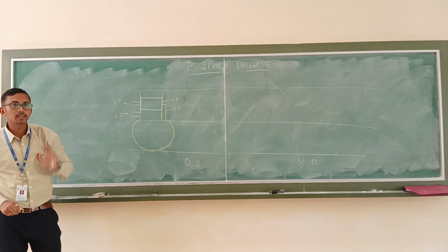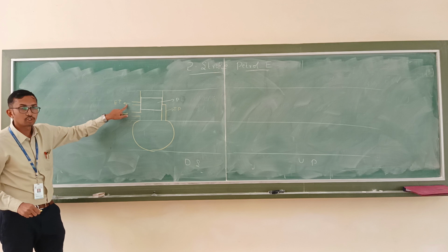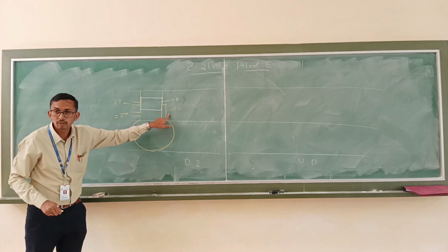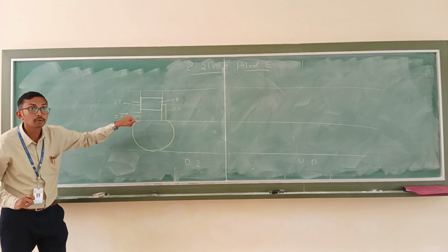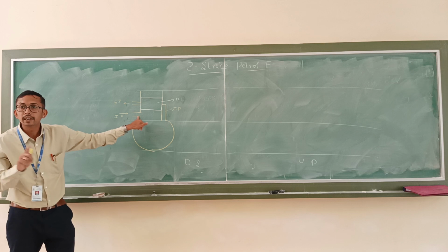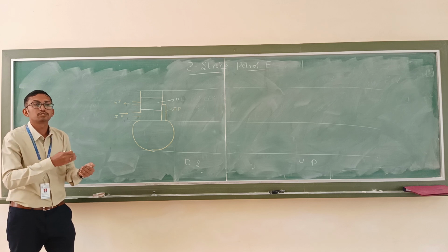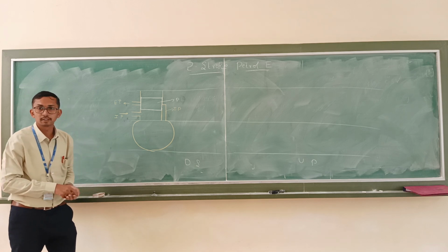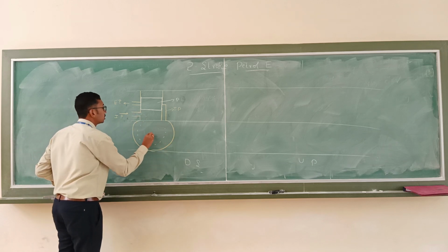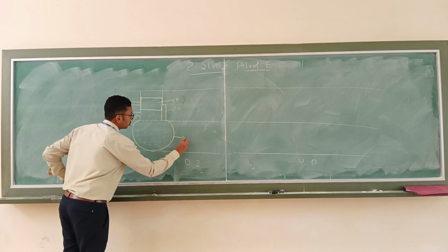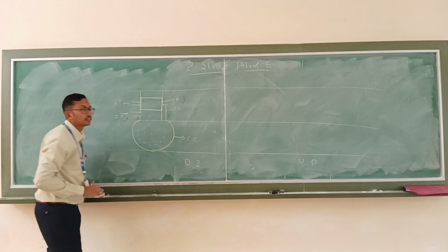When the piston is at top dead center, the exhaust port will be closed, transfer port will be closed. So which port is open? Inlet port. It is not input, it is an inlet port. What is the meaning of inlet port? The fresh air plus fuel mixture is going to enter the, which part is this? Crankcase.